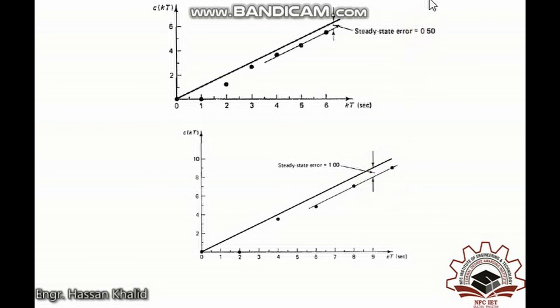So I hope that you have understood the mechanisms of the construction of root locus, and using those procedures how we actually evaluate the controller designed for our system, and the impact of varying the sampling time over the transient, and that of the impact on the gain as well have been demonstrated clearly in this lecture.